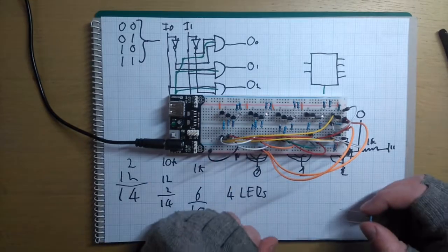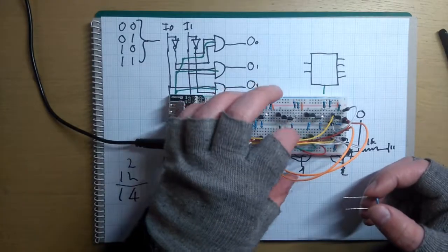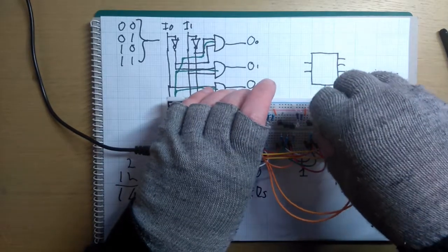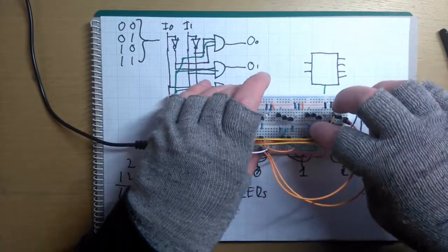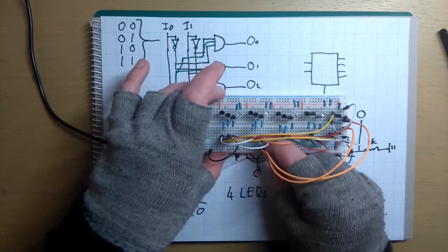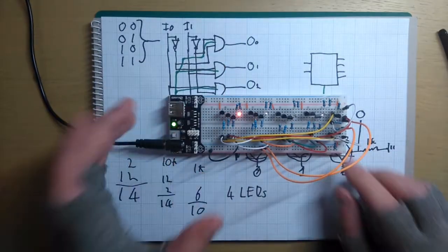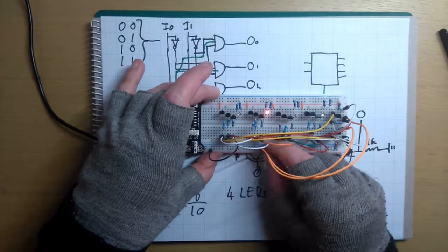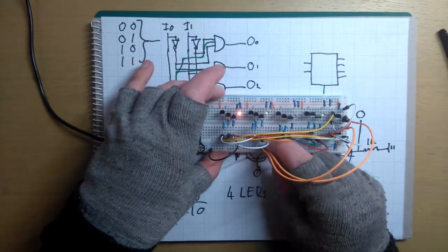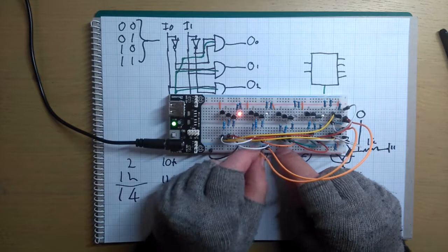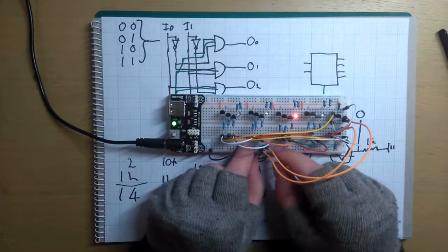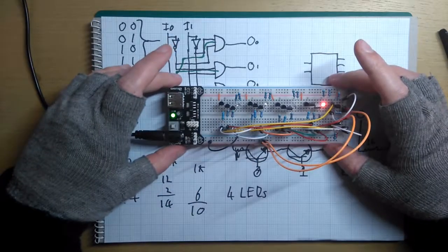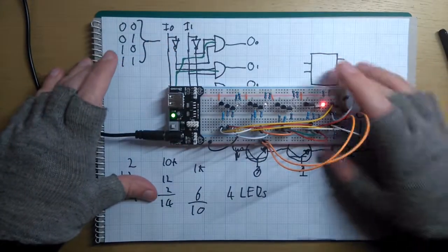Because I was looking at all the wires going, oh, maybe it's in the wire. Maybe I've wired something wrong. But no, I think the wiring is actually correct. It's literally just this resistor. So let's go through this again. Let's turn that off. Okay, so that's 0. That's correct. That's 1. So this should be 2. This is where the issue was. Hey, it works. And then this should be 4. Perfect. So that is our 2 to 4 decoder.